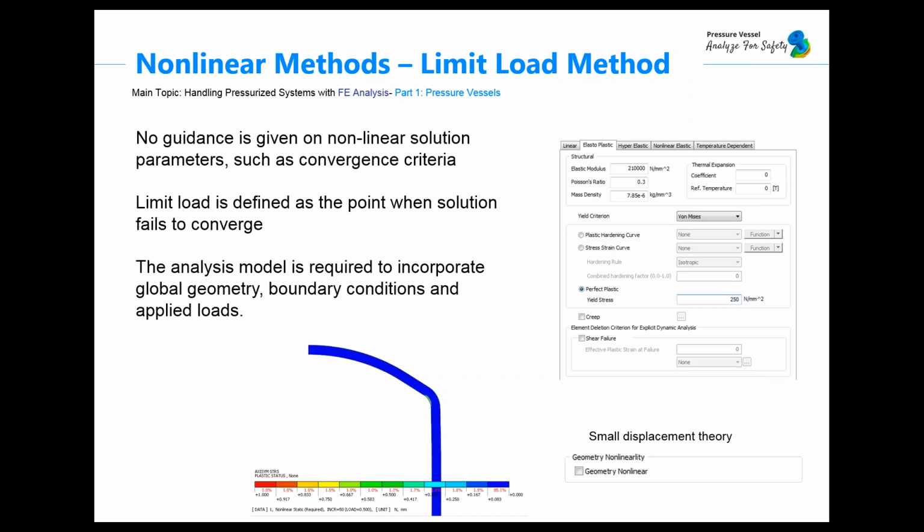Small displacement theory, how to apply that. Usually in the software there is an option which is called geometry nonlinear or large displacement option, or LGDISP parameter, depending on the code. For Nastran, for example, it is large DISP. And you have to be aware that for the perfect plastic material and small displacement theory, this check was supposed to be free. It's not allowed to check that.